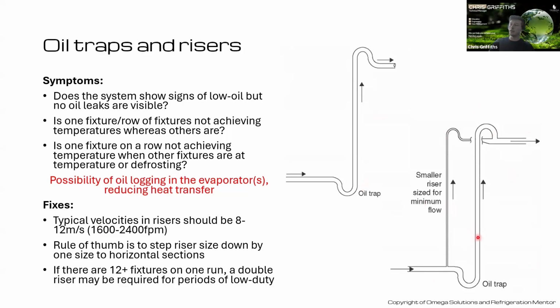So you'd be looking at part load, you'd base it on that smaller riser, and full load based on the larger one. You should really, if you can model it, base the flow on both parts of the riser combined. That's going to be very difficult to do in a piece of software like Danfoss. If it's returning at the main riser and that's what it's been sized for, great. It's not going to suffer by having the smaller one alongside it.